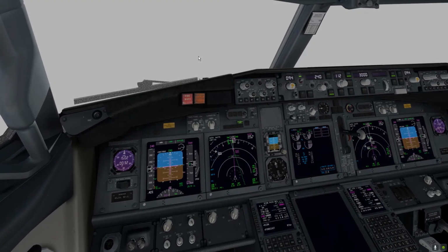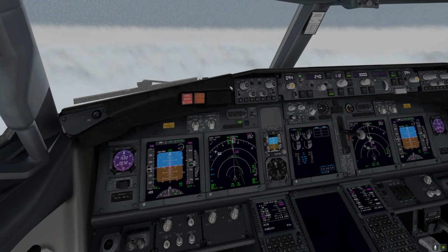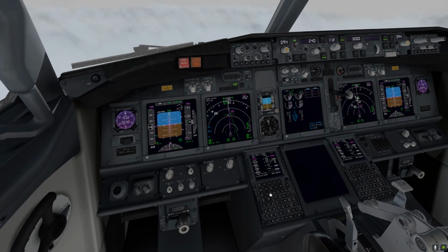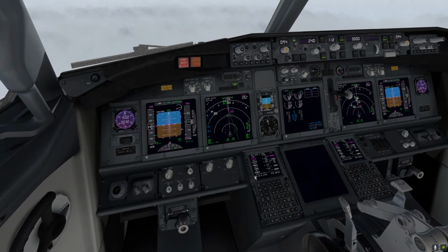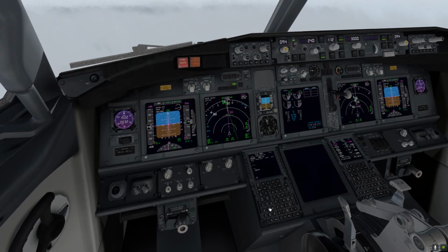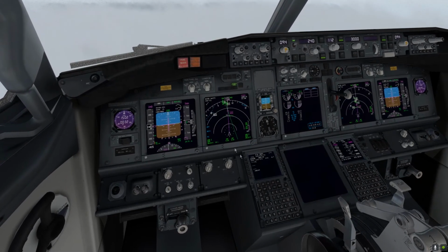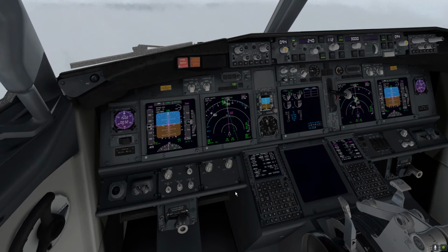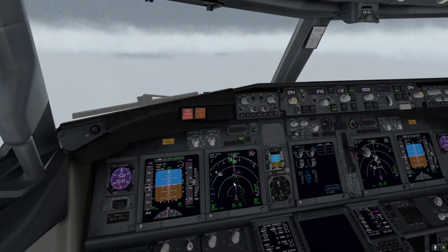The only extra thing that I can do, since our descent point in the approach is CAS-D, I can take this, put it into the fix, and draw a 2 nautical mile ring around it. This is per my company SOP.